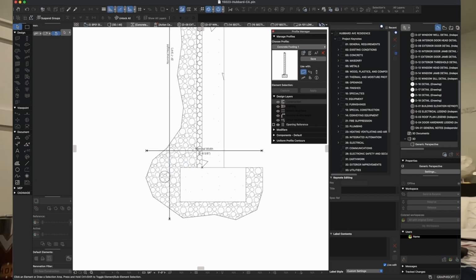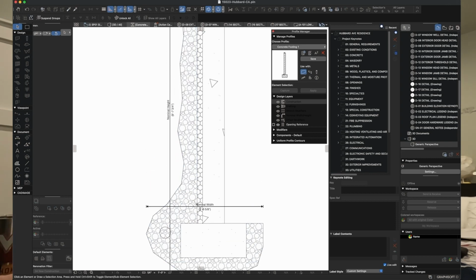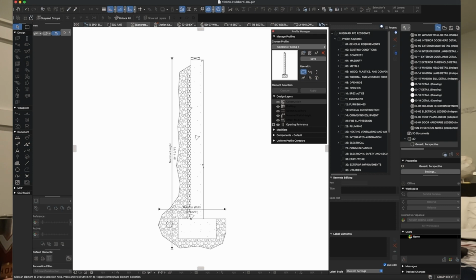All right, my next thing is to create the foundation drain. Now the foundation drain is typically a perforated pipe that, as the water comes up to this foundation wall, is going to flow down this gravel chimney. Because the gravel chimney doesn't have the soil in it, the water is going to flow a bit more freely.